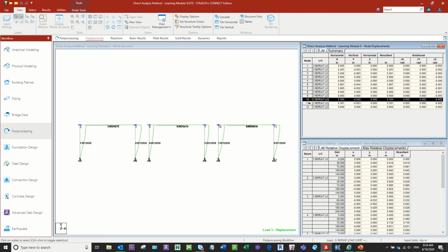And like I said, the structure is different for this one because it's nominal than it is for the other two because they're in their displaced configuration already. They have less lateral load. However, you can see that essentially I've generated a little bit more deflection here, which in theory would also produce a little bit more moment. So that's why you're able to essentially not have to worry about tau sub b or the modeling the imperfection as well.